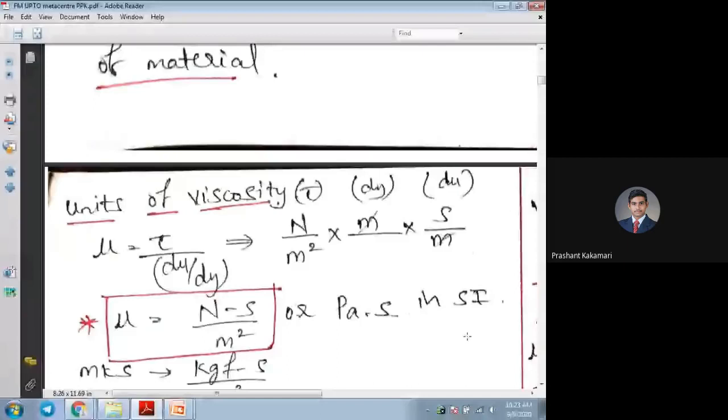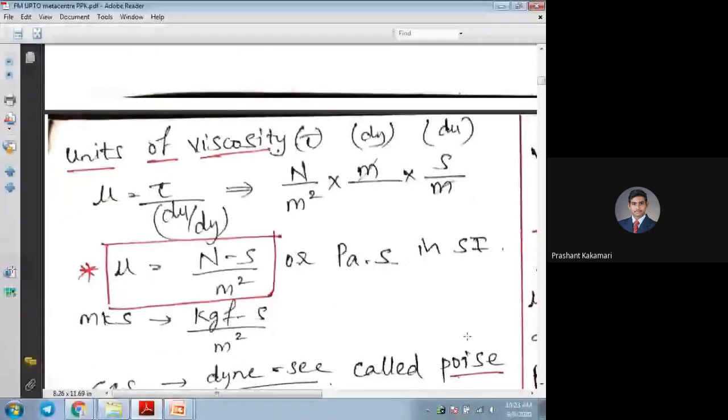So this viscosity is measured in various forms. For liquids, viscosity is inversely related to temperature: as you increase the temperature, the bonding between the molecules reduces, or the volume of the liquid increases. So the resistance, the viscosity value, will decrease for the liquid, and it can easily flow. For this, one example you can take is coconut oil.